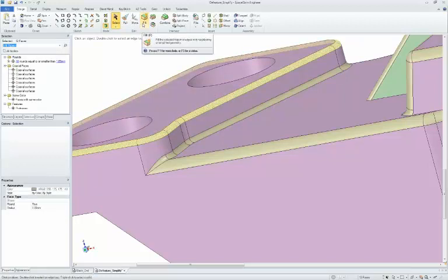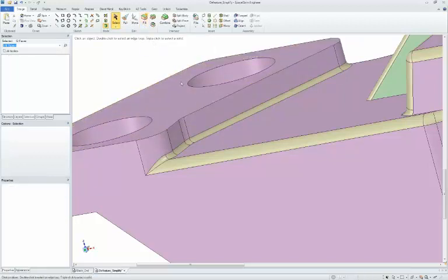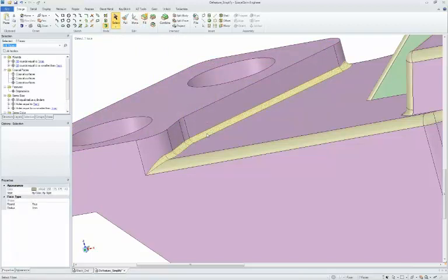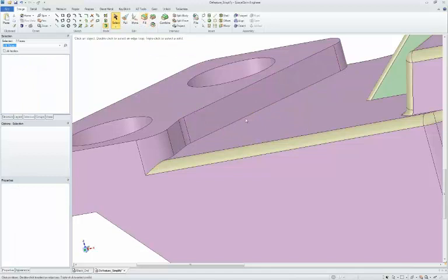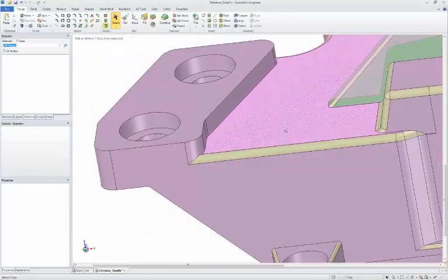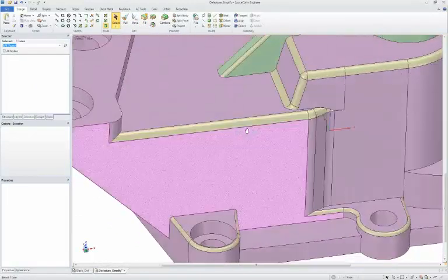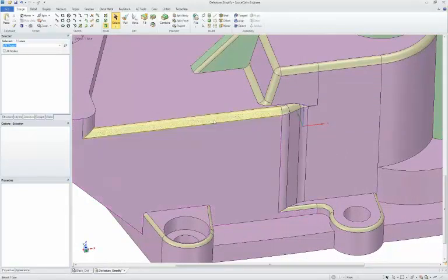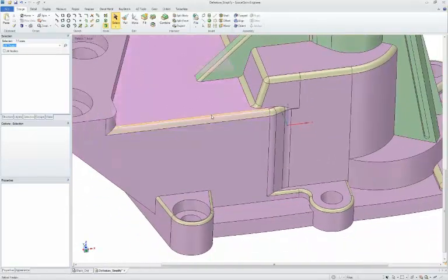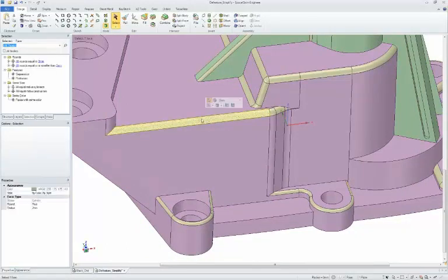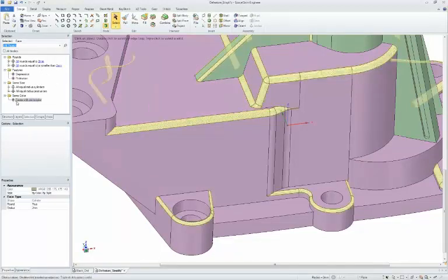I'm going to be showing a lot of different things of how we fill in and defeature things in the model. But the key thing to remember with this is how quickly and easily you can do it. Because a lot of times 5 minutes of defeaturing can save you half an hour of runtime, depending on how many times you're going to be running your analysis, especially when it's this quick to select on rounds and find them and remove them. And speaking of finding them, this is that selection panel I was talking about.